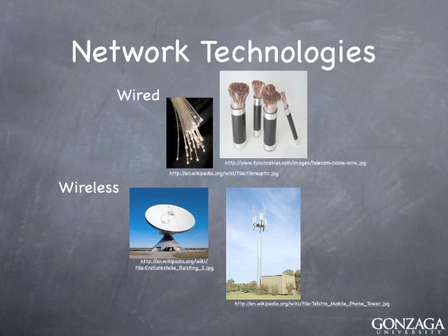If we're looking for a single source solution that is best delivered by a particular vendor, and they've architected it in such a way that they have a soup to nuts solution, then that's going to point us maybe to something that's a bit more proprietary and fixed to whatever transport domain they might have had. Say they might have a wireless network transport because their devices all have wireless controllers and they're all speaking on some sort of proprietary RF protocol that no other vendor works with, but is highly groomed, highly tailored to their solution.